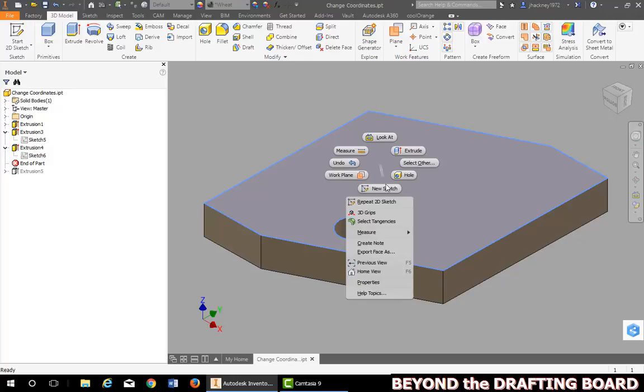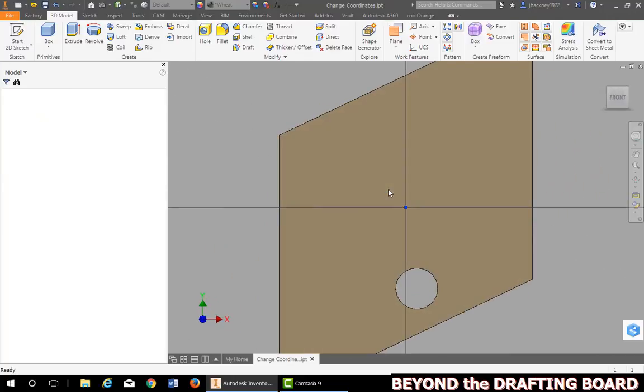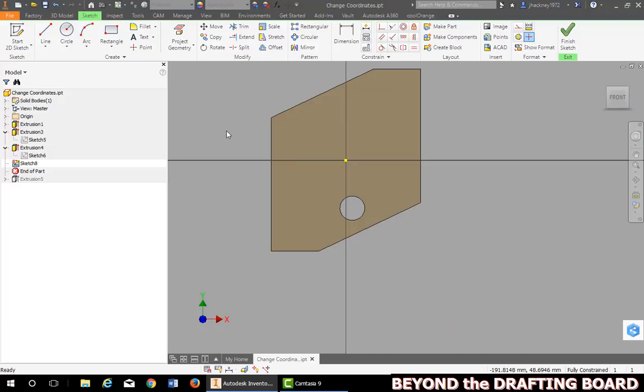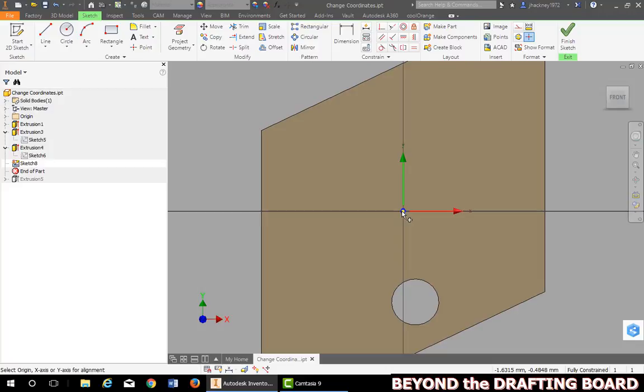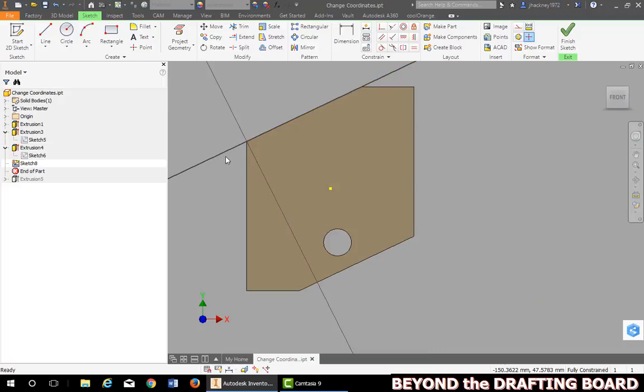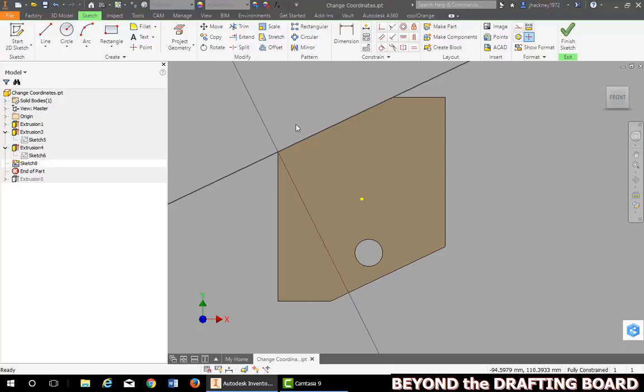Let's make our sketch first. It is in the original orientation. Go to my constraint drop down, pick edit coordinate system, click on the blue ball, put it in the corner where you'd like to work off of, pick on the bar representing the axis you want to align. If it's going the wrong direction, right click and flip axis, then right click and say OK. Notice the coordinate system has been rotated, the x-axis being along the edge.